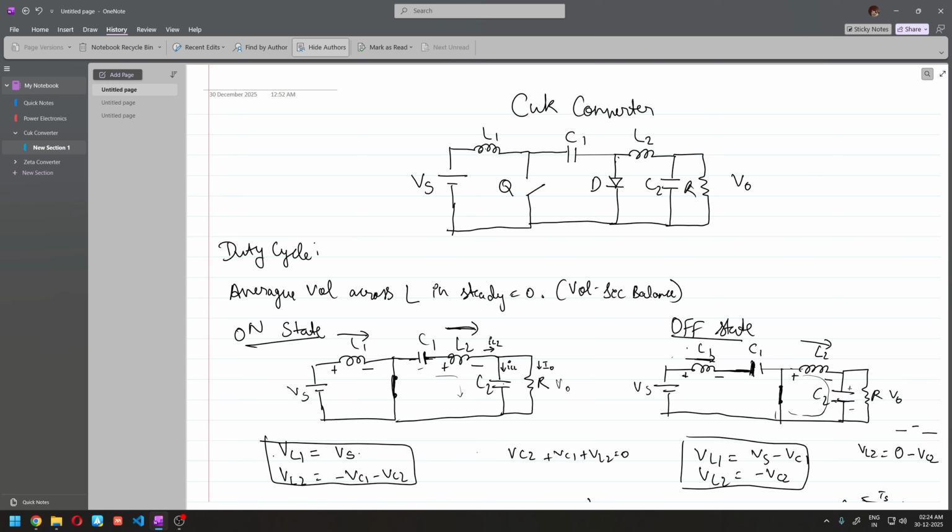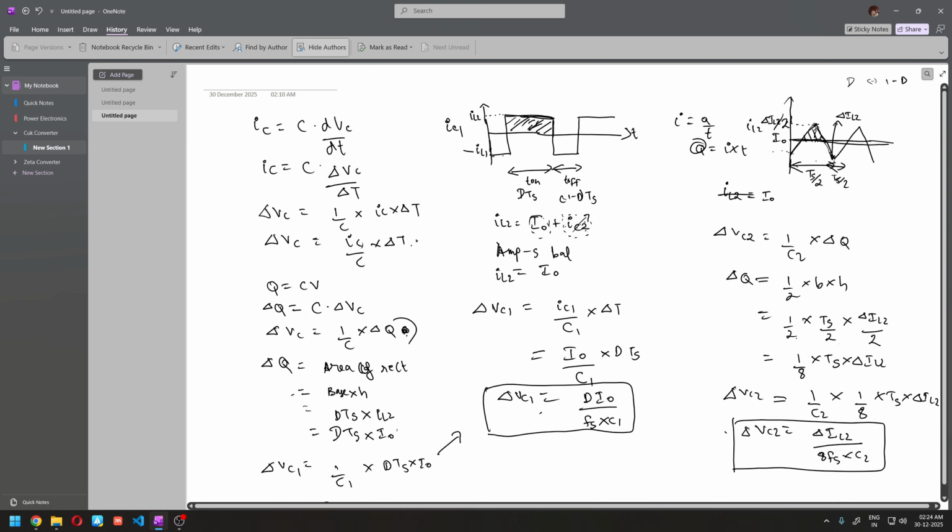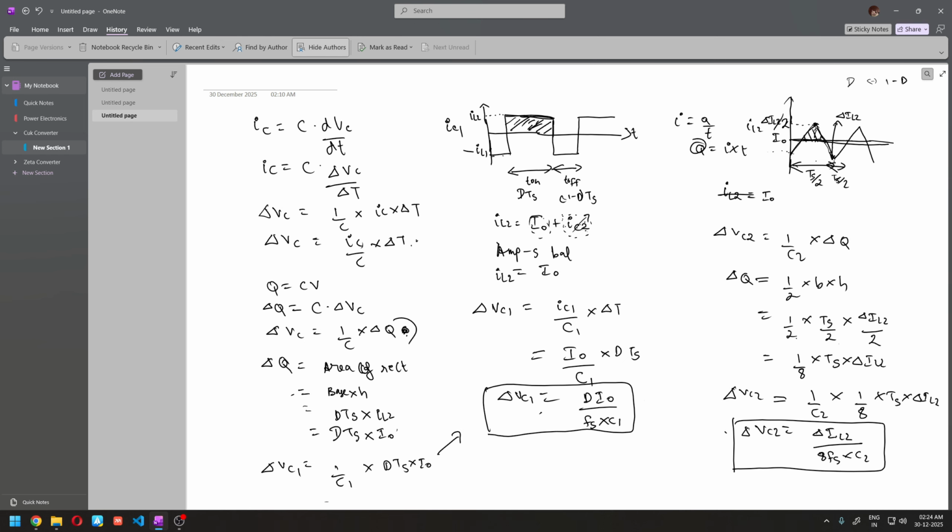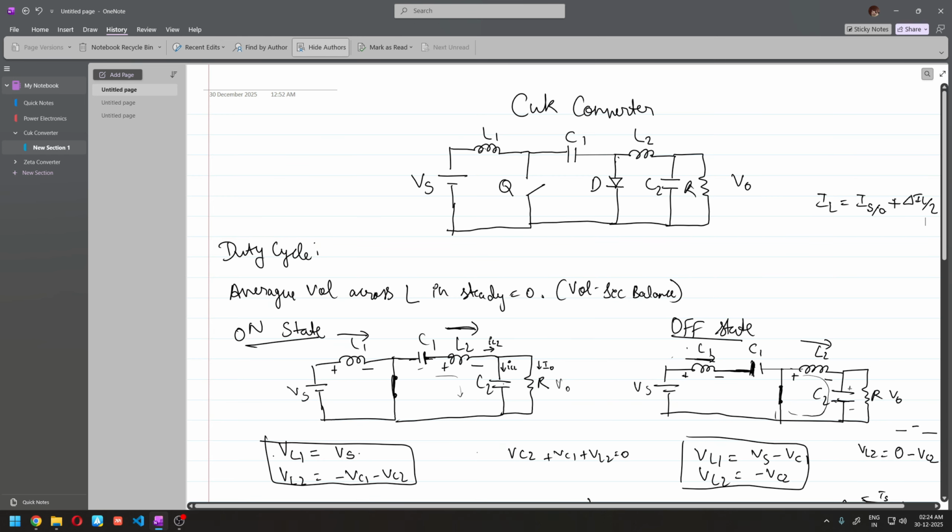and you have to take into account the maximum saturation current of this inductor, because at any point the current through an inductor is going to be the steady state source or output, in this case this on the source, this on the output, plus your ripple component. So the peak of that ripple, as I showed here, is going to be the peak value. So your inductor has to be able to withstand that. So you need to consider this.